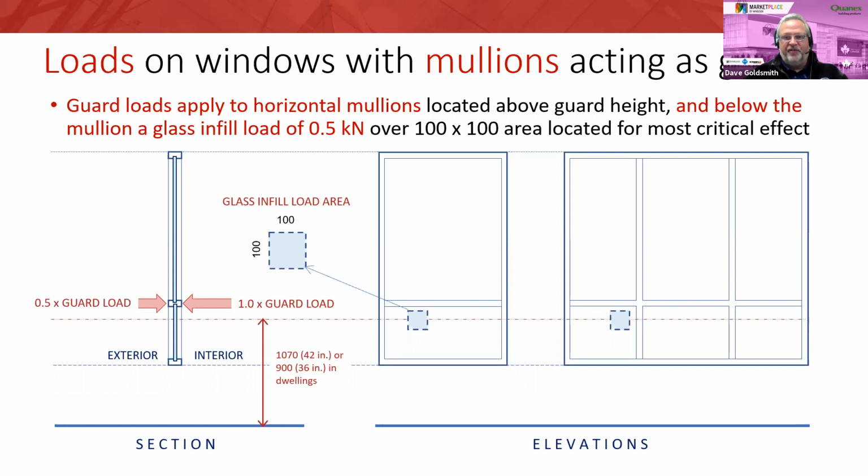Absolutely. But then in a glass railing with an infill, that infill is going right down to the floor. Right. So if that glass broke, then a toddler could take a plunge, right? But you could also have a pony wall with a guardrail on it, right? So in other words, you could have this exact condition as a guard on a balcony with 18 inches or 24 inches of glass sitting on a concrete wall or something like that. With respect to actual railings and guards, I don't think they'd be able to waive any of the requirements. That's right.